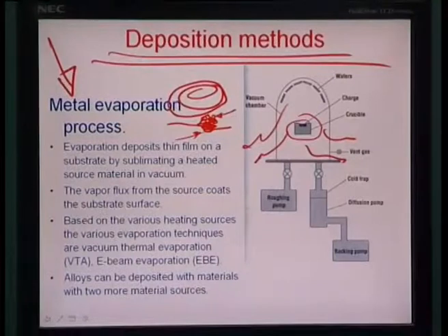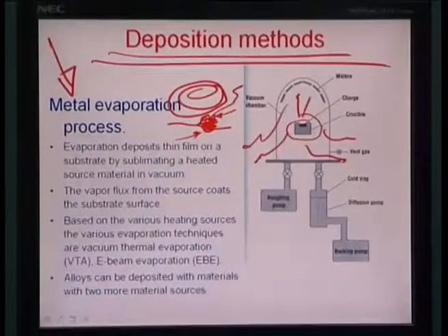So assuming some of these data, if you have a wire which has a lower melting point, you can of course red heat this tungsten wire so that it is just below the melting point and still in a solid structure, and in that case the heat delivered is good enough to evaporate all this material out from the crucible into the atmosphere, and this is high vacuum. So therefore there is no chance of contamination, and the high vacuum is created essentially by two mechanisms.